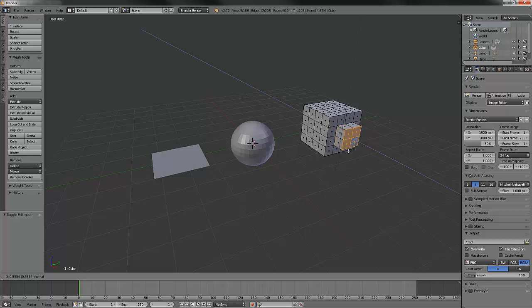Now, by default, Blender will calculate the direction of the faces and choose a default axis for the extrusion that makes the most sense. Most of the time, it's exactly what we want. But you should note that we can control the axis, just like everything else, by selecting it with our X, Y, or Z keys. However, when extruding faces, this often is not very handy. But, as you will see in the future, we will have cause to use it on occasion.